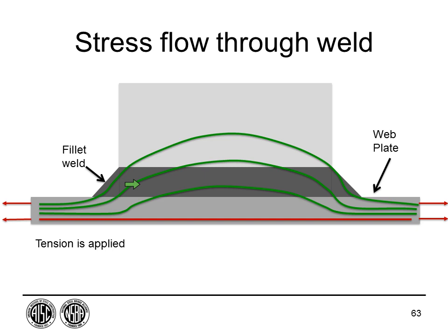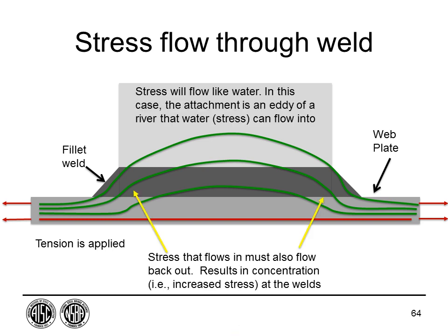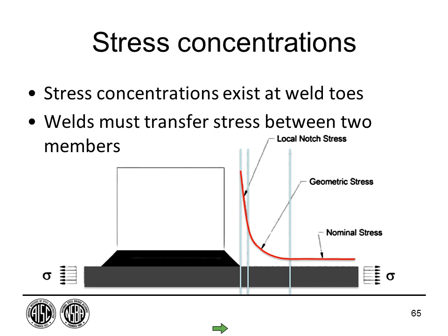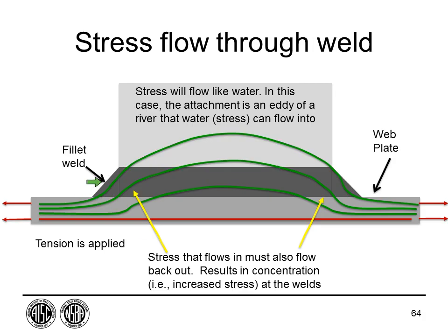The stress didn't get the memo from the engineer about not entering into the element that was welded to it. So it enters into that component. And as you can imagine, at the terminations I'm going to have some stress concentrations in these locations because of the stress simply going in and out at the terminations. Along the length, it's actually quite smooth.